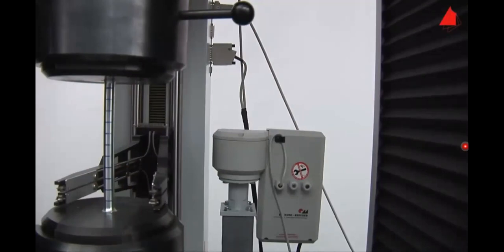It will not reach an upper yield point and a lower yield point. It will reach its upper yield point and then directly start its plastic deformation. It will not come down to its lower yield point. There is nothing like that, no lower yield point. There will be one yield point only, and that will be the yield strength of that material. You will see that during this particular experiment.